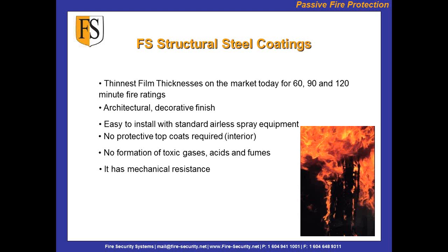Really, it's only about 23 or 24 days, but saying 30 days is always a very safe time. But you're not going to be doing your external fireproofing in the rain and thinking it's going to fully cure either. Most of that fireproofing would be done undercover. Humidity is a factor as well. We would prefer low relative humidity. If it's high humidity, it's going to take longer to cure. But in low humidity, like the Middle East countries with very low humidity and high temperature, it cures very, very quickly. Sometimes too quickly if it's too hot.